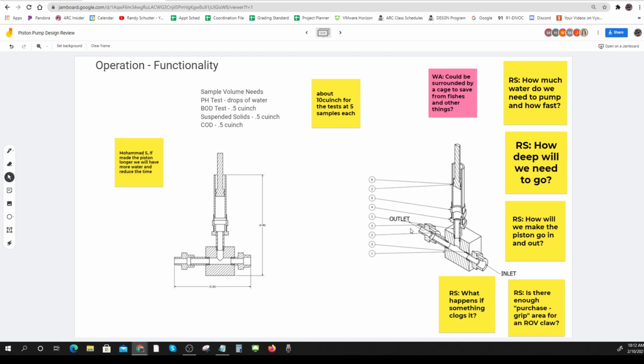So the next one is if I'm 10 feet deep. Here I am. I just ran a sample and I go to a new spot and the pump plus the tube is filled with my old sample of water. So we call the next thing the purge volume.